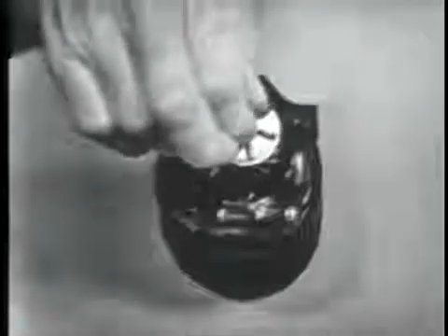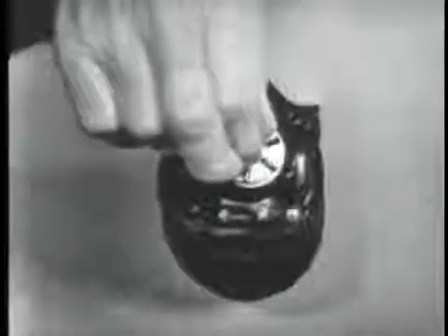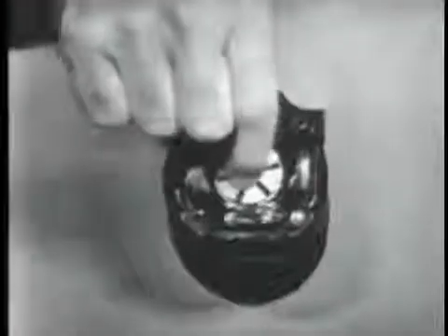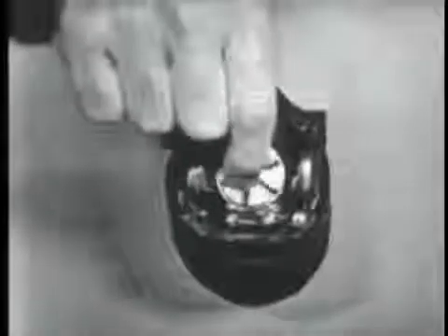These field windings have AC applied to them in the proper phase relationship. They are producing a rotating magnetic field, which is easily proved when this chunk of iron is dropped into the field. Proved, Tom, not really easily, because the magnetic field is attracting the rotor toward the stator field. Now we've got it in there now, and if I let go of it, it rotates.